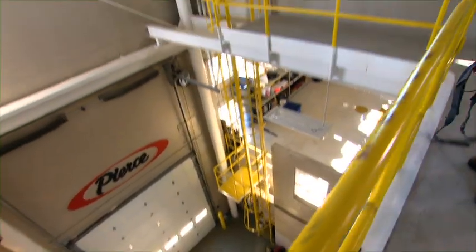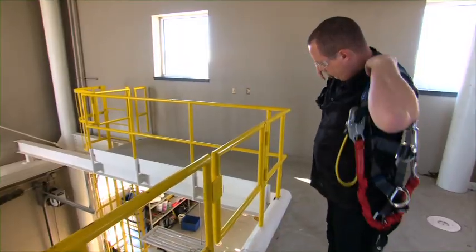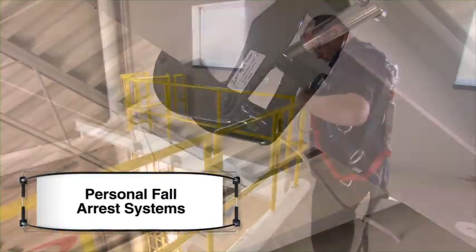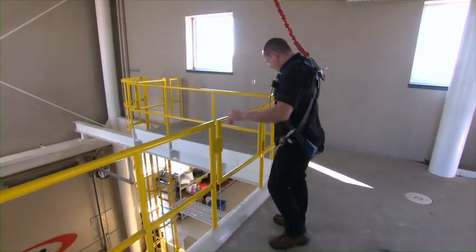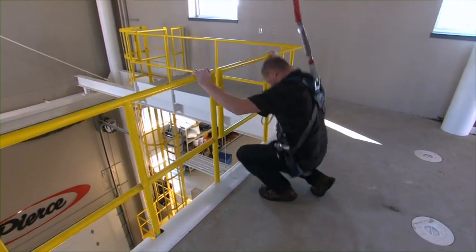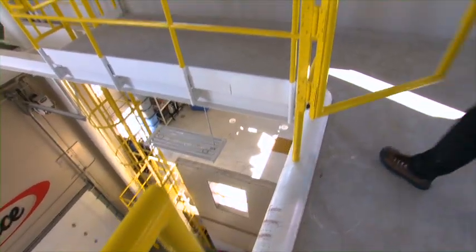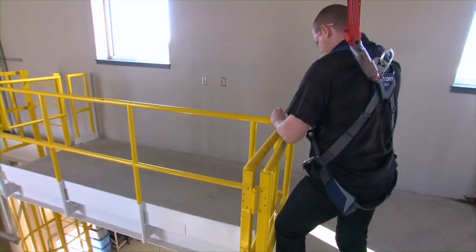PPE is your last line of defense and minimizes your exposure to a variety of hazards, including falls from elevated work levels or platforms. PPE includes personal fall arrest systems, travel restraint systems, and positioning devices. Personal fall arrest systems are used to stop an employee in a fall from an elevated work level. These systems consist of a body harness, anchorage, and connector. Connections may include a lanyard, deceleration device, lifeline, or a suitable combination.